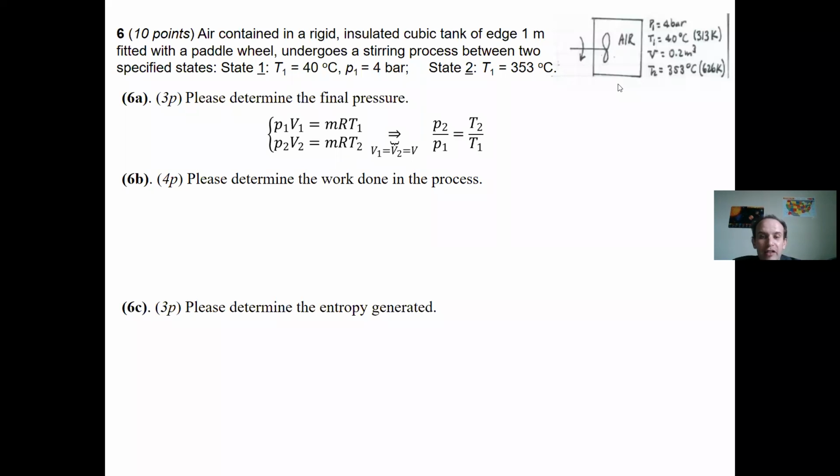Why can't you use the relative pressure relations, P2 over P1 equal to the ratio of relative pressures, that you may see on the chart? Very good question, but the answer is quite clear. Because this is not an isentropic process. The equation P2 over P1 equal to the relative pressure ratio is for isentropic processes. Here it's not. That's why I tell you, don't employ formulas if you don't know where they originate from. You should always know what to use.